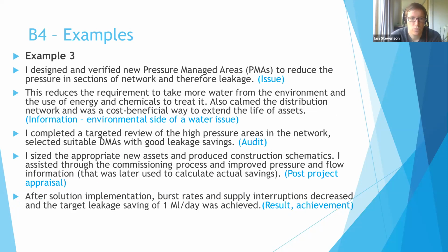A third example here, looking at a clean water example. I designed and verified new pressure managed areas to reduce the pressure in some sections of the network and therefore leakage. So one sentence to lay out the issue. This reduces the requirement to take more water from the environment and the use of energy and chemicals to treat it. It also calmed the distribution network and is a cost beneficial way to extend the life of assets.